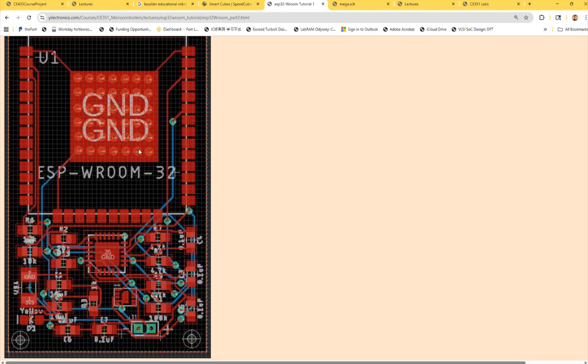In that case, when you are picking a voltage regulator, usually they will lose some voltage. It's called a dropout voltage. So if you are converting a voltage to a smaller voltage, the regulator has to be very carefully chosen. For example, the really cheap regulators lose like 1.2 volts.